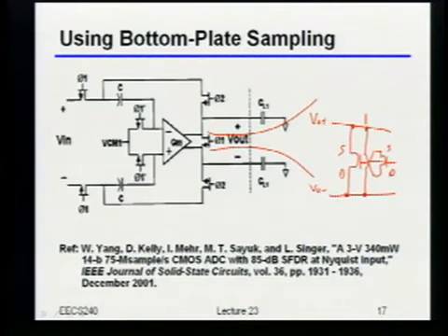And by the way, in case you didn't remember, this was probably a good idea anyway, because if you wanted to match anything, you probably wanted to have the transistor so that current was flowing in both directions. In other words, you always used two fingers and had current flowing both ways. Okay? So same idea here: if you want to be absolutely paranoid to make sure you don't get any extra errors, you better make sure the thing is completely symmetric. And the only way to do that is indeed to do something like what I've drawn here. Does this make sense to everybody?